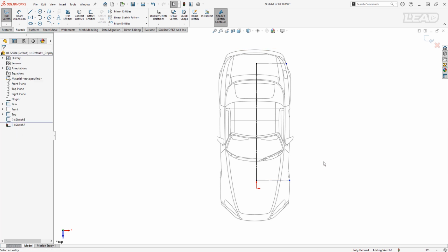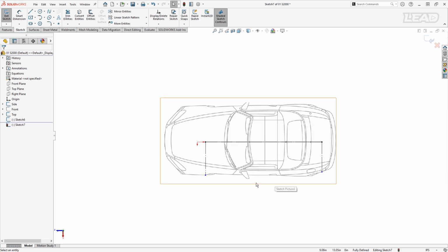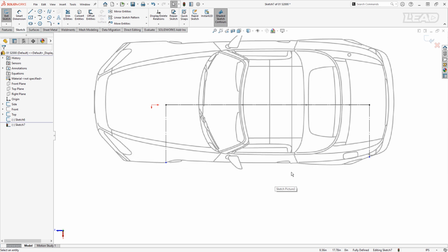And the main reason that I do this is because whenever I'm working with projected curves, I'm going to go ahead and rotate this down. Holding Alt and the arrow keys will allow you to rotate the view. I just like to view it this way because of the widescreen. So anytime you are creating a projected reference, it's extremely helpful to know that the second curve, in our case the top-down curve, is going to align to the endpoints of the first curve.